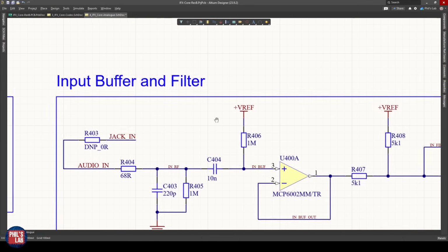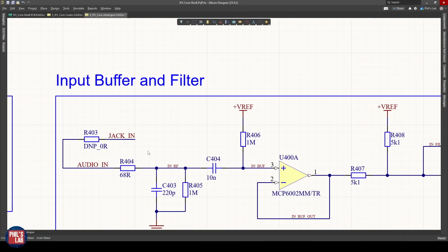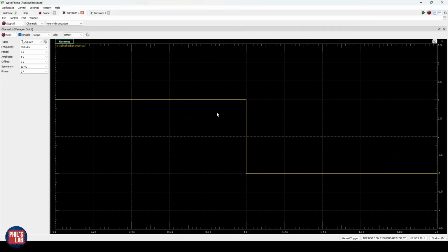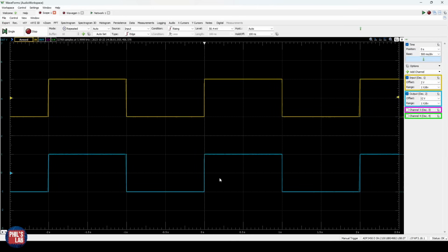What we have to keep in mind though is that this is not a DC coupled connection. On this DSP board, I'm actually using AC coupling as I have to bias my op amps at half the supply voltage, so we do have this high pass filter at the input as well as at the output. This means for a square wave in, without any processing, we will simply see pulses out because we're effectively high pass filtering our signal. Now without the effect enabled, we have our yellow trace at the top, which is our input signal, our 2-second period square wave, and at the output, this is without the circuitry enabled, so it's a direct true bypass feed through, we are getting a square wave at the output because it's perfectly just a wire connection.